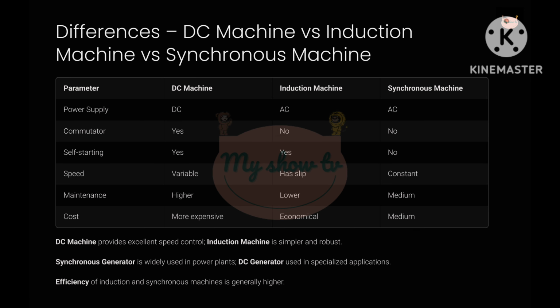Slide 7. Differences: DC machine vs induction machine vs synchronous machine. This slide helps compare the three types of machines. 1. Current type. DC machines use direct current. Induction and synchronous machines use AC. 2. Commutator. Only DC machines use a commutator to convert AC to DC internally.